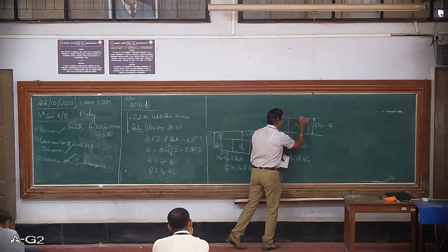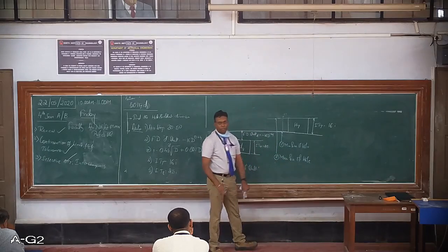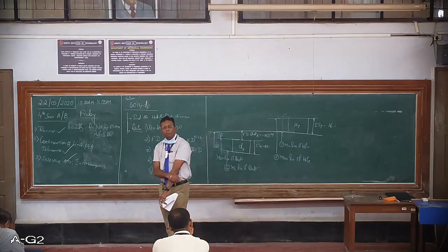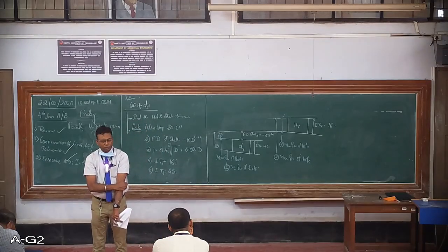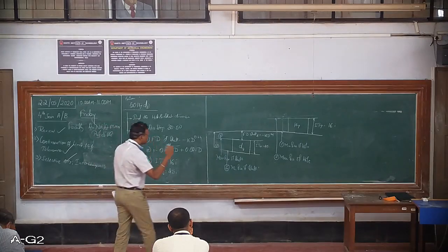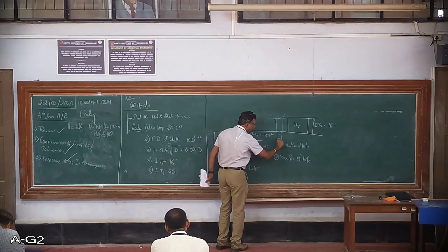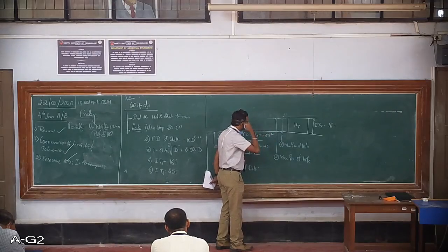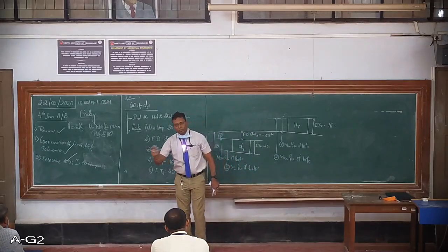Next small corollary, if some hole is given as 51 by chance, obviously it gets rejected. Now, can it be considered for remachining and then used in the assembly? Obviously not, it is not possible. Hole size is already beyond the maximum size, we cannot reuse it. It has to be rejected. If the value is something less than this, it is within the acceptable zones. Anything less than this, we can send it back to machining operations, enlarge the hole and use it. It involves an additional cost, that's a separate part.